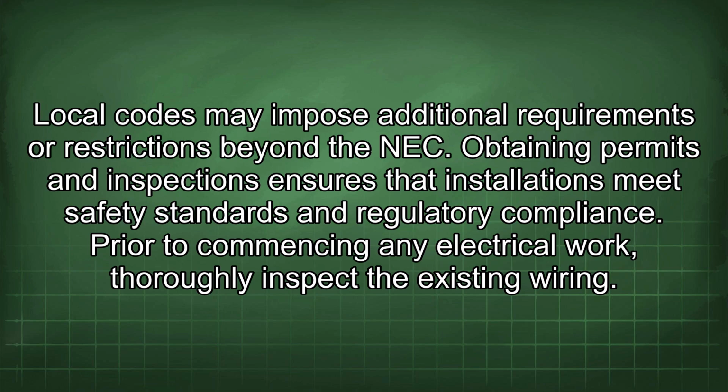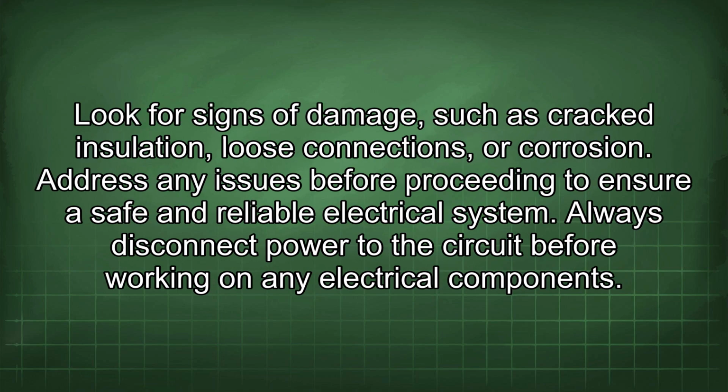Prior to commencing any electrical work, thoroughly inspect the existing wiring. Look for signs of damage, such as cracked insulation, loose connections, or corrosion. Address any issues before proceeding to ensure a safe and reliable electrical system.